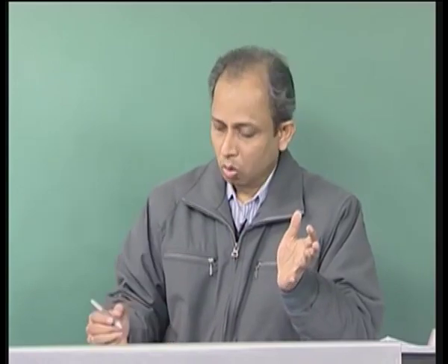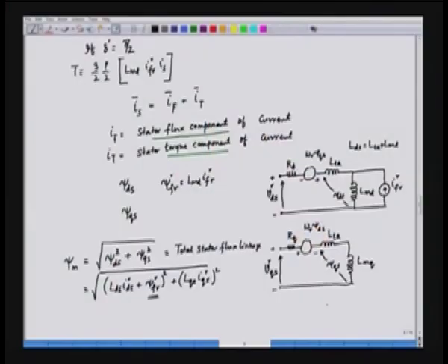speed. So, we have a function generator, and the function generator gives us the variation of psi m with the speed. So, this is how it varies. So, we have psi m in the y axis. Psi m remains constant up to the base speed, and after that this enters into the field weakening mode.